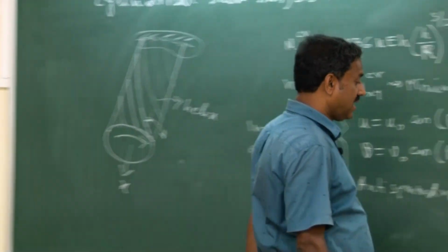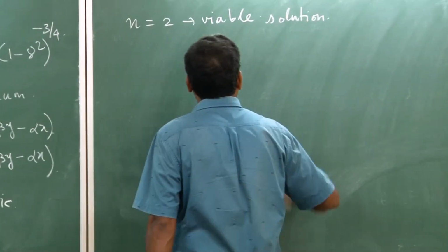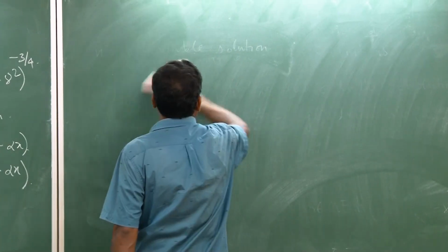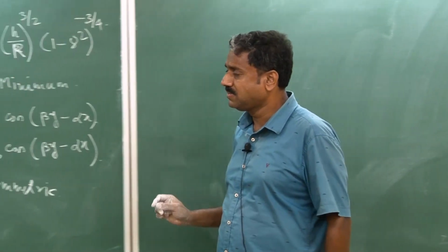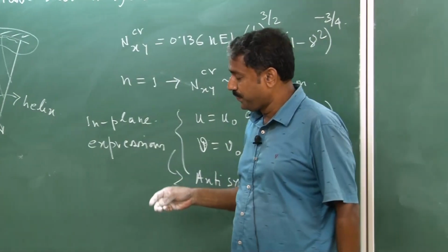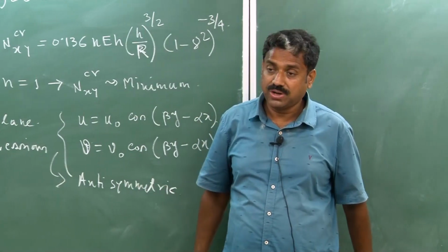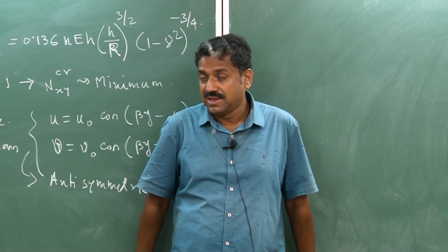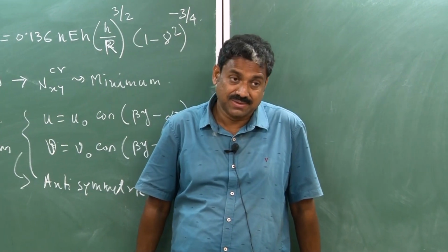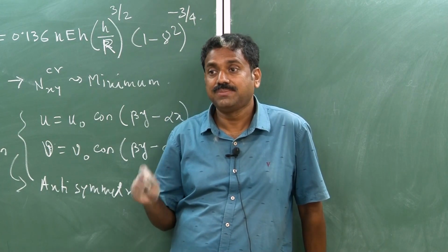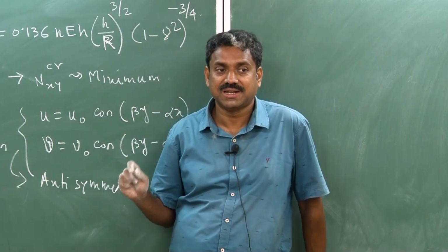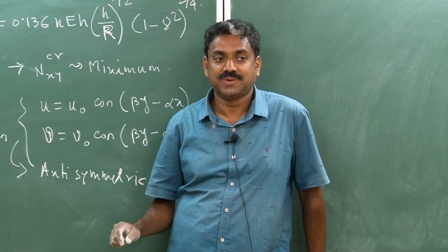A cylindrical cell under torsional load, this buckling is not imperfection sensitive. So, with this I will stop here. You see that we have used Donnell's equation to solve the critical load for different cases. Please note that in the cases in which it is not imperfection sensitive, that means there is no multiplicity or closeness of mode, Donnell's equation gives quite accurate, good results, because that matches with the experiment.